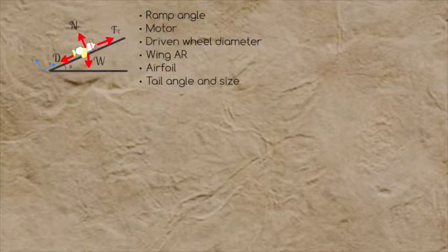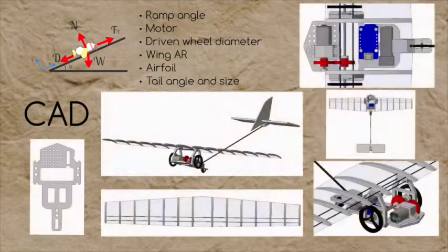During the design phase, the dynamics of the glider on the ramp and in the air were modeled on MATLAB and several parameters were iterated upon in order to maximize the range. This was done along with a CAD design from which a weight estimate could be obtained.